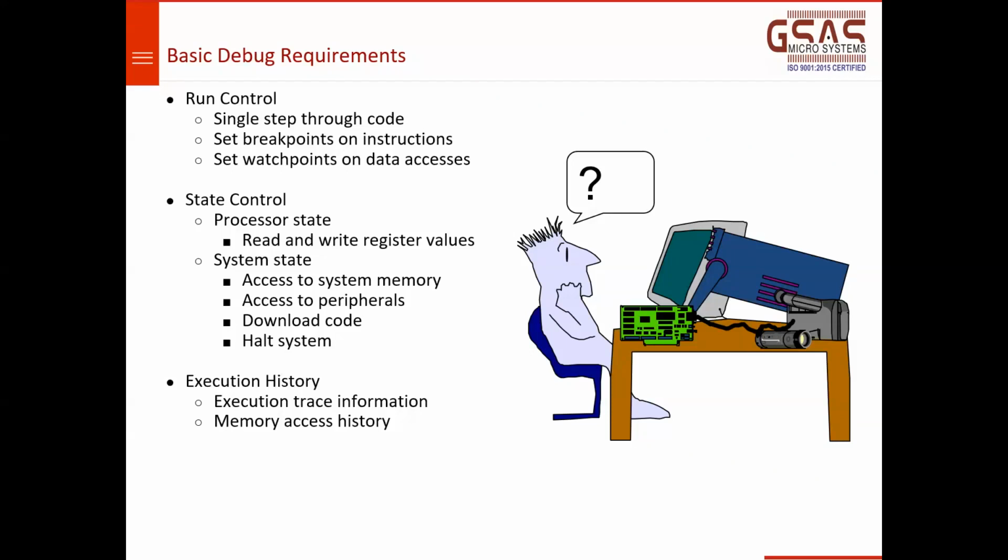Whenever there's a logical error and you don't want to debug, or there is no debugging support for the processor or whatever microcontroller you are using, then there is no way other than a trial and error method: try to replace some C statement, build the project, download the code to the board and see. But the higher end MCUs come with something called debug support.